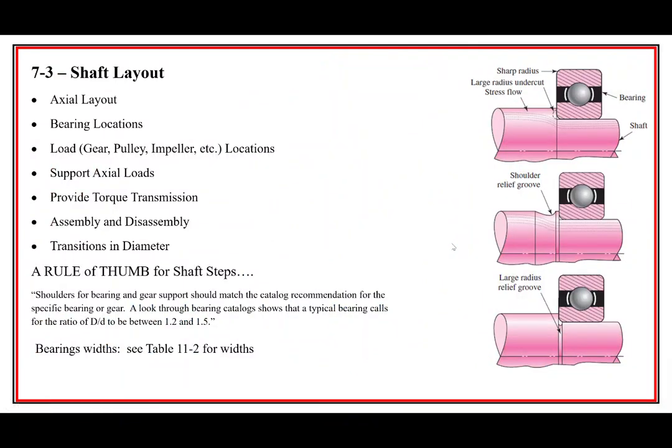See, shaft layout. I'd already talked about the axial layout, and of course the bearing locations, but also some of the details where the bearings land up against this step of the shaft, right? The purpose of the step is to definitively establish that when you put a piece of equipment, the gear or the bearing, onto the shaft, it is exactly there in the axial layout and will match. Some considerations: the transition that happens between one step and another step, right? So I guess that's actually right there.